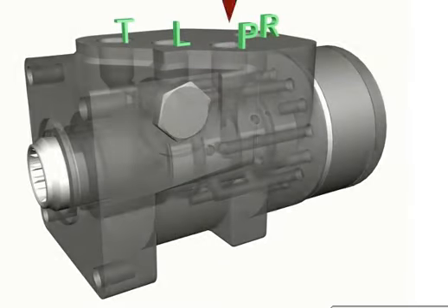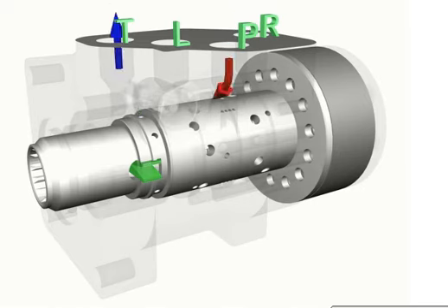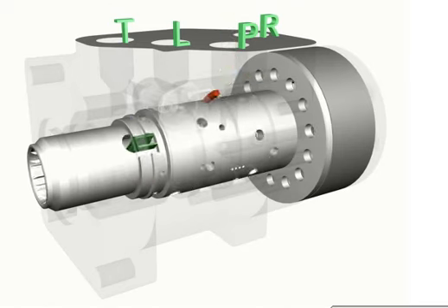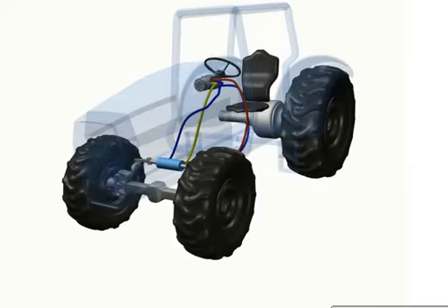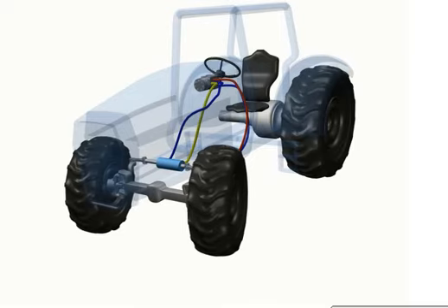Without rotation of the steering wheel, the centering spring holds position of the spool and sleeve, and the fluid flow is allowed to pass through the pressure port to the spool and sleeve and to the tank port of the steering unit. Rotation of the steering wheel counterclockwise rotates the spool and the sleeve against the force of the centering spring, allowing fluid to pass through the rotating spool-sleeve valve.